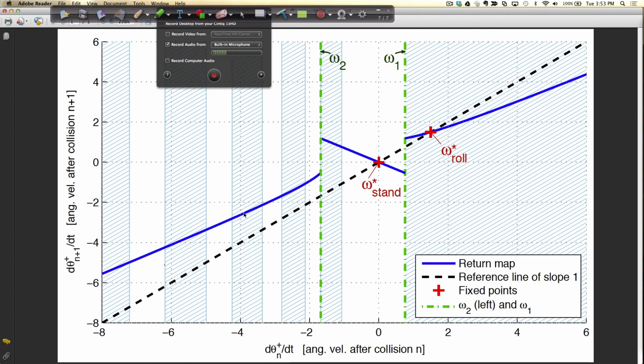If I start over here, I end up there, and there's strips that go out, and they expand as you go backwards, with the expansion rate exactly equivalent to that cosine 2 alpha of dissipation. So this whole thing is a contraction over time, every one of those steps gets a little closer, and I can completely understand what happens. I end up in one of those two fixed points with the basin of attraction completely characterized. It's the only walking system you'll completely understand.